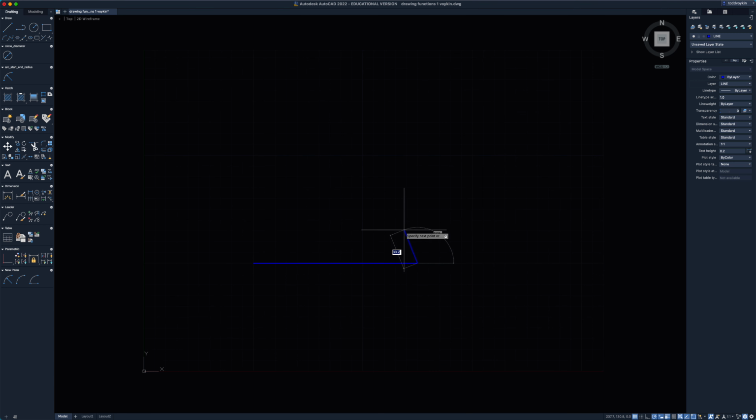Now it says to move up in a vertical direction. So again, I get that green line and 150. Then off to the left, green line is right there again, 150. And now there are sort of 3 ways to close this. So one, I can literally type close, hit enter, and that's done. If I hit Command Z, it's going to go back out of here and force me to do it again, which I can do very quickly.